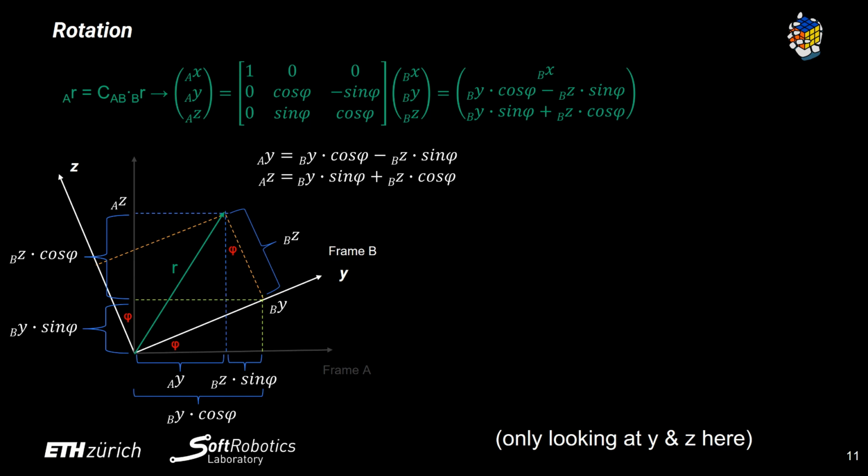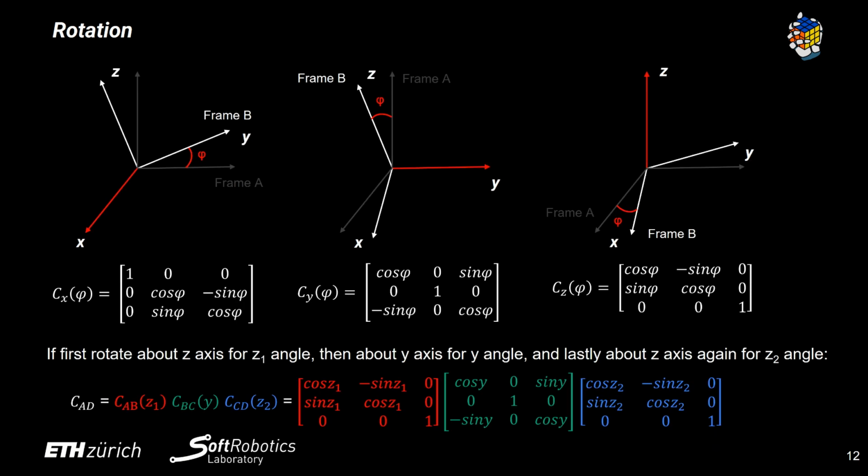a lot of sense. Another way of understanding the rotational matrix is that it is essentially the projection of unit vectors of the frames. All rotation movements could be decomposed into combinations of elementary rotations. And to get a rotational matrix for the movement, you just need to multiply the elementary rotation matrices in order of occurrence. To get the vector after rotational motion, simply multiply the rotational matrix with the vector. This could also be used to transform the coordinate frame of the same vector.